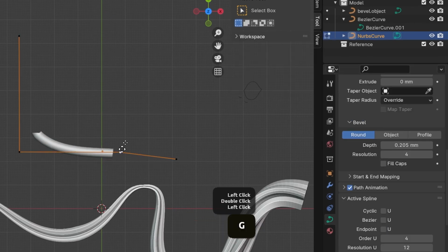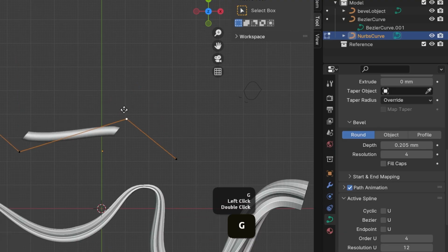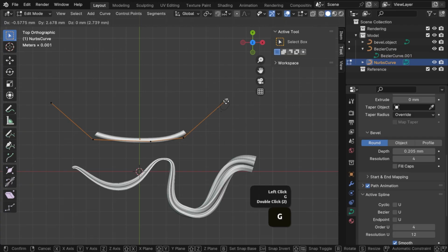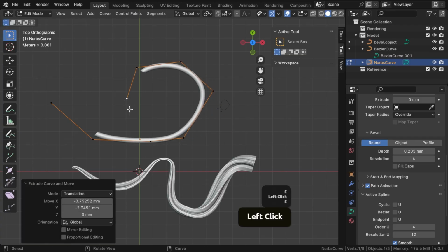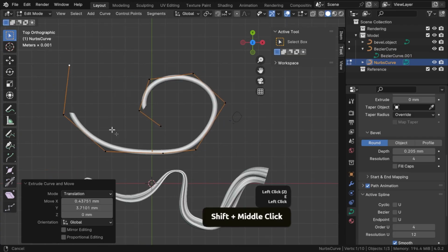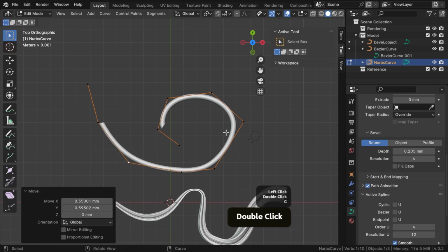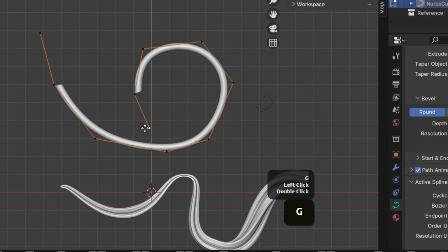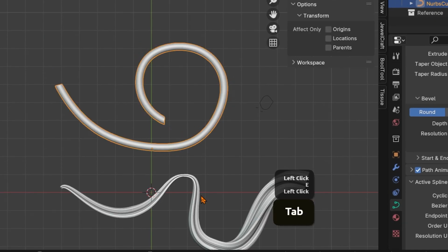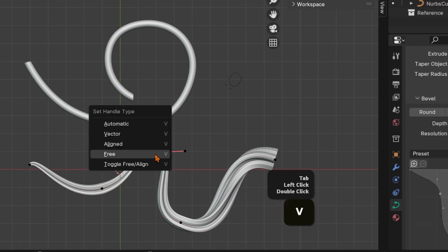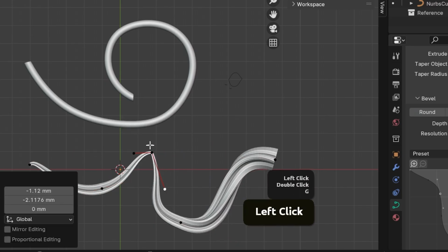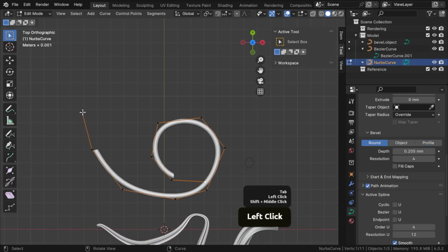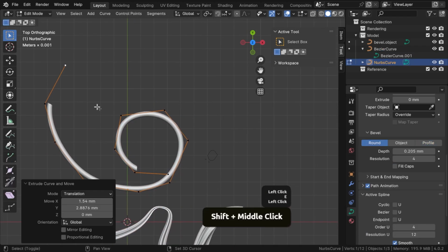So if you move these control points, the curve approximates the placement, and you can press E and then the curve will follow, and you can make it follow these control points. So you don't control the curve as directly as with the handles, but the advantage is that it is pretty much guaranteed that you always get a nice curvy shape. Whereas with the Bezier, if you toggle it to free, of course, you can sometimes mess up your nice curve. Okay, so this is the Nurbs curve, and you may notice that the end of the curve does not align with this last endpoint.